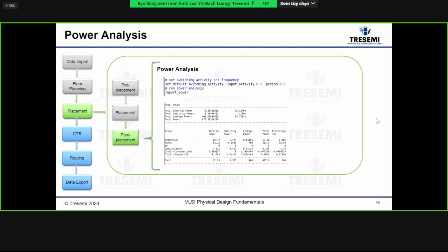So back here on page 15, you see the power analysis, the power consumption is really, really difficult to simulate, simply because for leakage, it's easy. Leakage is just a total source drain area or gate area. As you recall, the gate leakage is the most important, the most dominating source of leakage. But the source, drain, and gate leakages can be calculated by calculating the total of active areas.